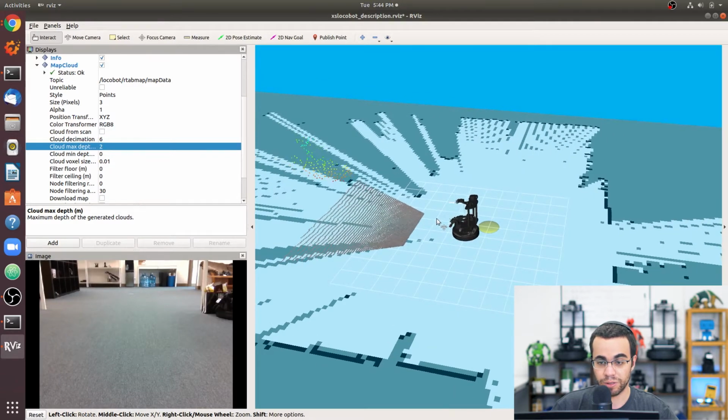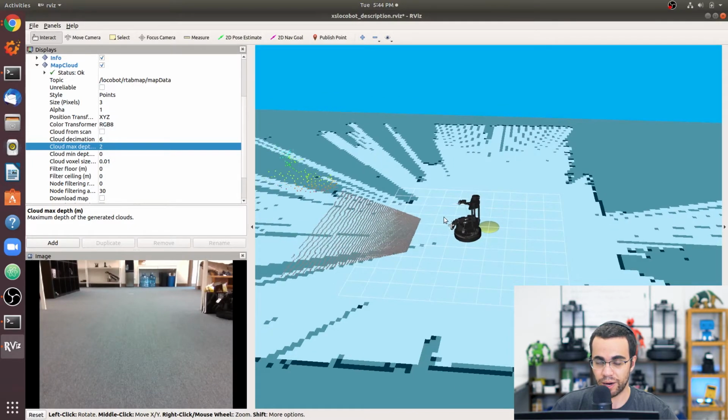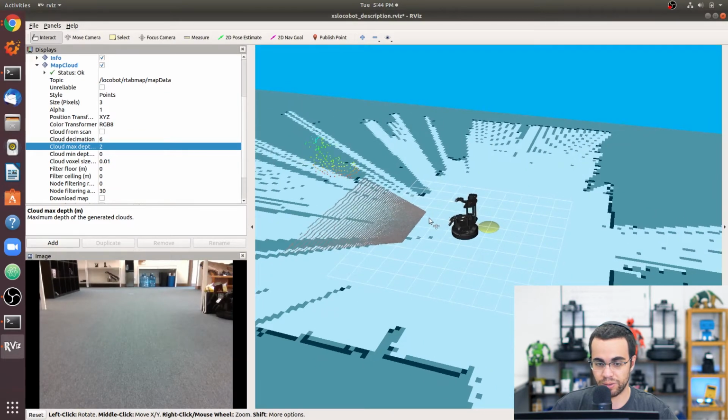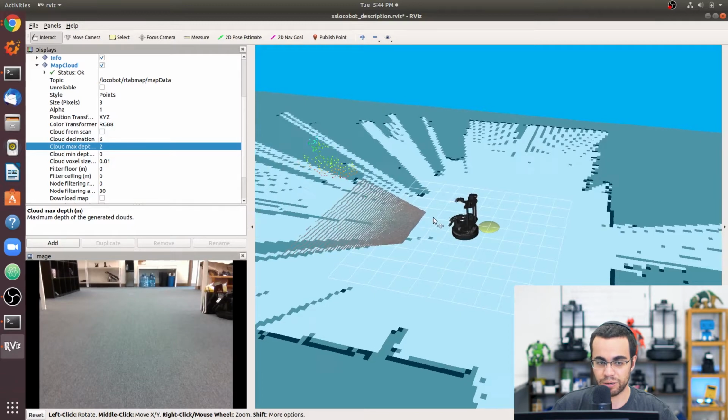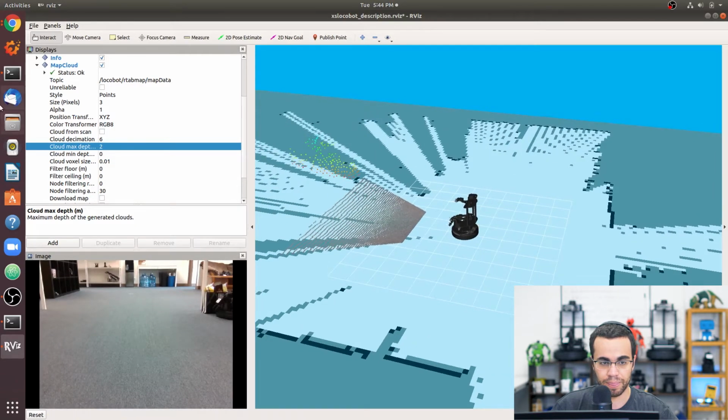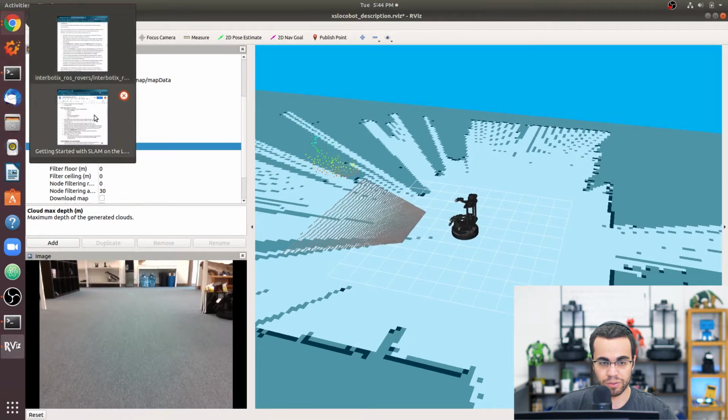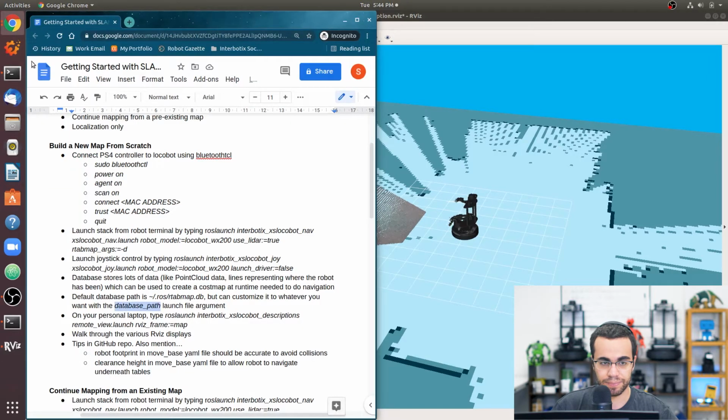For this particular RealSense camera, actually, they say that the ideal range is between 0.3 meters and 3 meters, even though the max range is technically 10 meters. But just to be even more conservative, we're going to set it to 2. And I found that you get pretty nice point clouds just doing that. All right, so back to some of these tips.